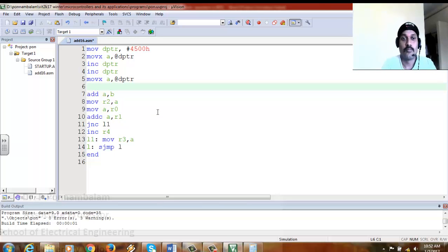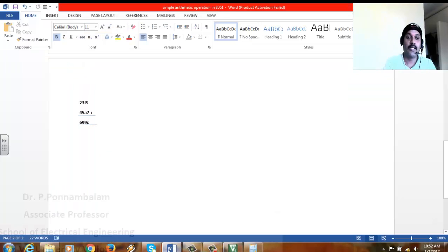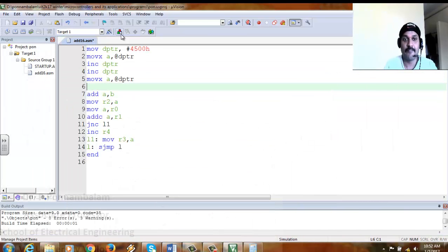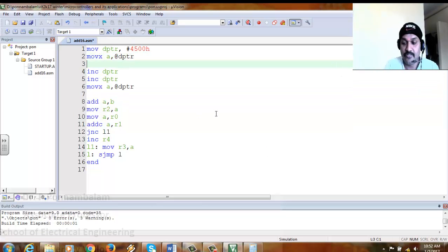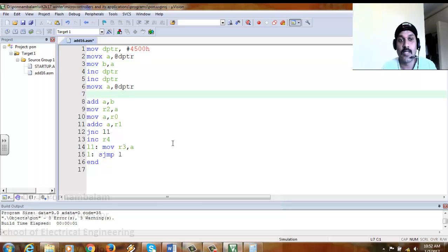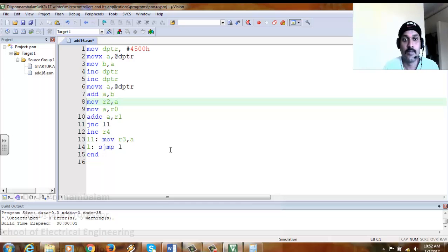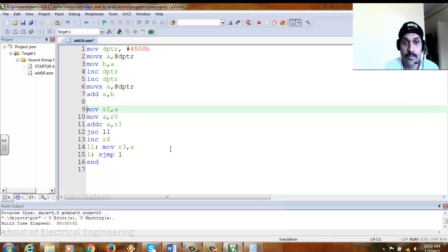So obviously we'll be obtaining A7 and F5. So A7 and F5, mov b comma a, so that the first value is stored into the b, and 2 times I have incremented. So now the value has been fetched into the accumulator. So addition happens here. Then after adding, what I'll do is store the result. If I want, I can store the result.